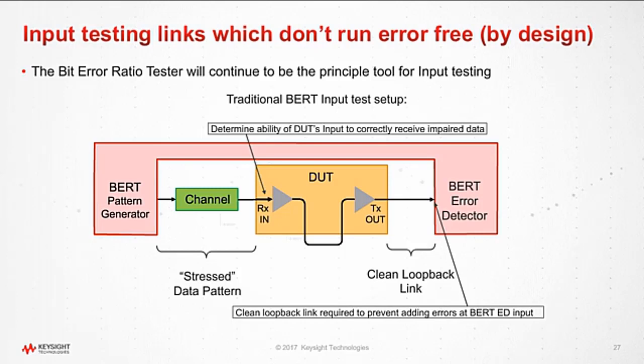So what happens if we have errors in that? Well, any error where my arrow is drawn in that signal, caused by any corruption mechanism, will be counted by the error detector. The error could actually be at the input of the error detector itself. Those errors are added to the real errors that the DUT experienced. Once we have that, we confound the results, because we're going to overstate the error rate, since additional errors are produced by the input of the error detector.